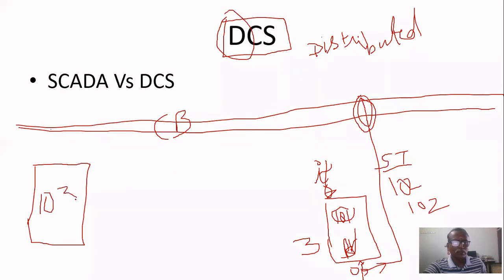103. It knows that this controller has to control this 101 process. That's why it knows that the smart transmitter 102 will send the process variable. That's why it reads all values but rejects all values except the data transmitted by 102. That will be taken by this controller, which calculates the controller output M of t.